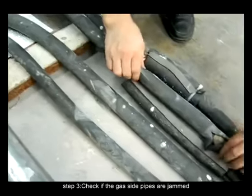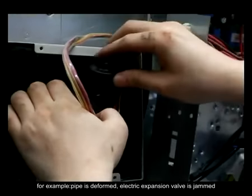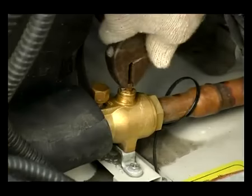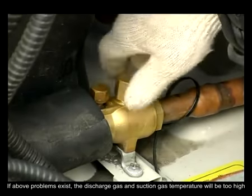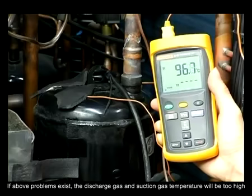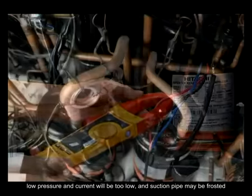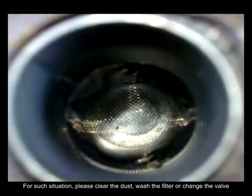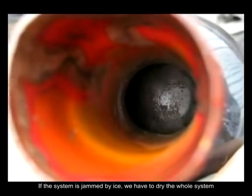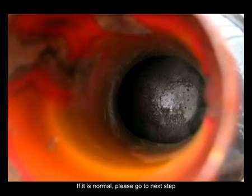Step 3. Check if the gas side pipes are jammed. For example, pipe is deformed, electric expansion valve is jammed, the low pressure ball valve is not open or filter is jammed, and so on. If above problem exists, the discharge gas and suction gas temperature will be too high, low pressure and current will be too low, and suction pipe may be frosted. For such situation, please clear the dust, wash the filter, or change the valve. If the system is jammed by ice, we have to dry the whole system. If it is normal, please go to next step.